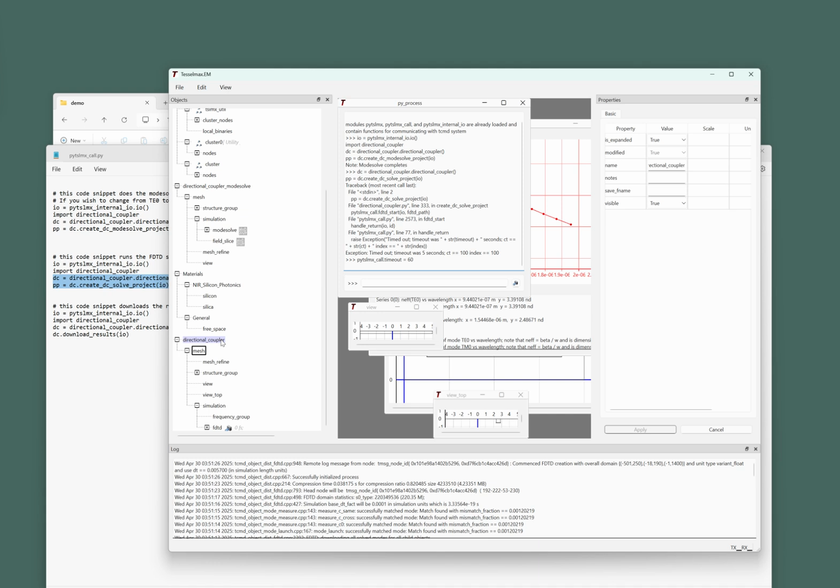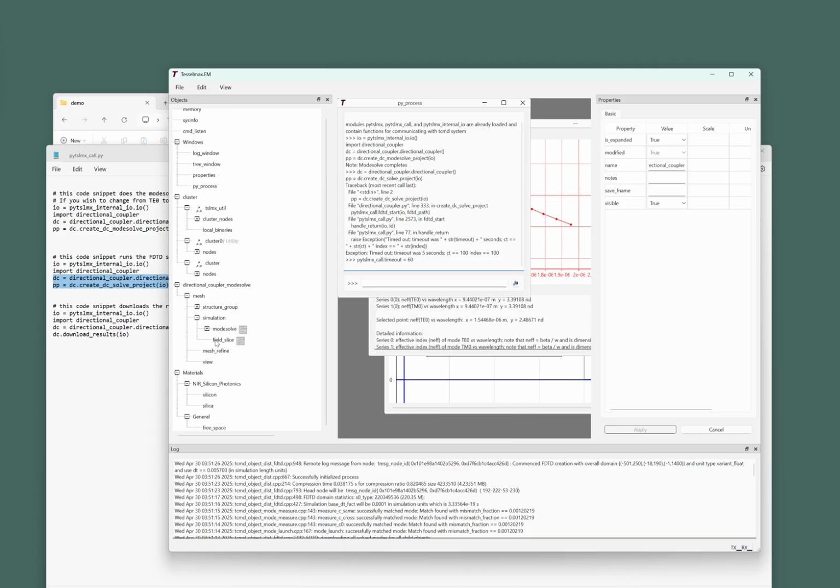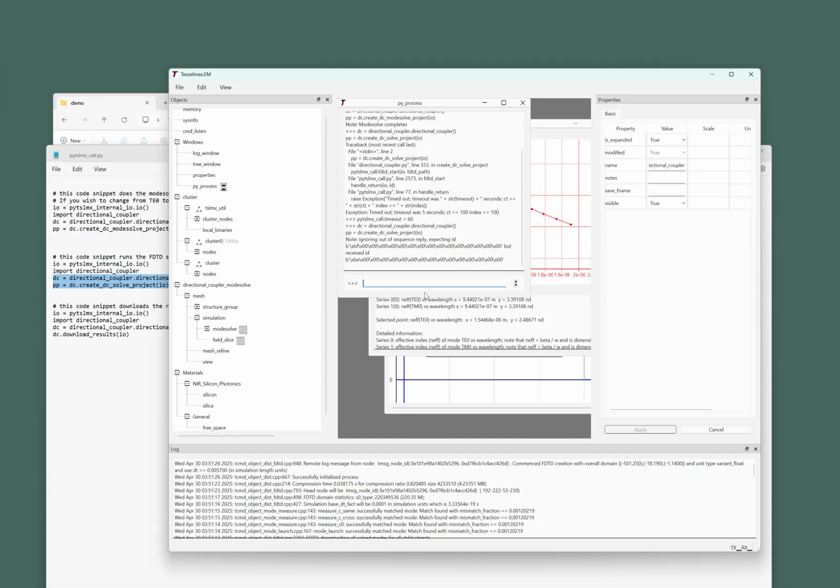And now I'm going to go and delete this thing. It actually instantiated the simulation on the remote server. I'm just going to delete this. That's all you have to do. The simulation will be cleanly shut down and exited. And now we can rerun this whole Python thing with a new timeout. There's some error message about a previous thing that is ignored, but you can just ignore that. It's just going to run again, and this time not time out. So, a little troubleshooting thing.